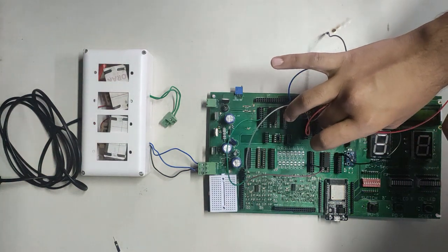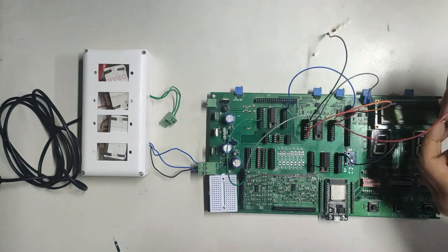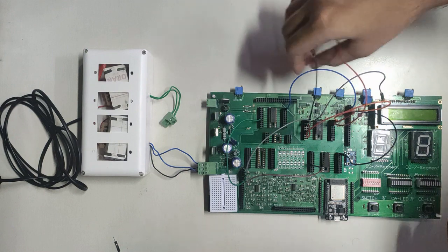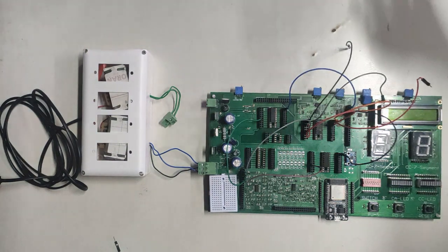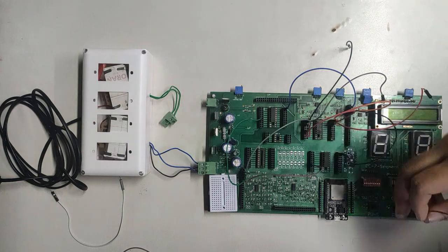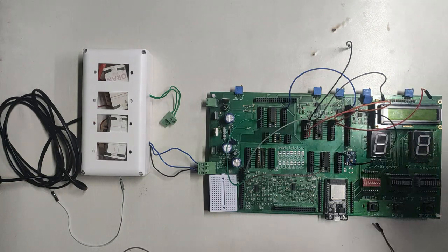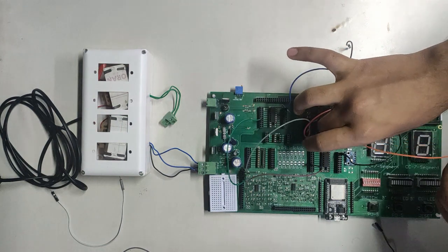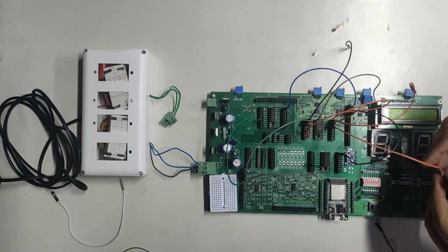And this is our third input, as full adder requires 3 inputs, so these 3 are our inputs, and the output of the second XOR gate is nothing but A XOR B XOR C, which is nothing but our sum.